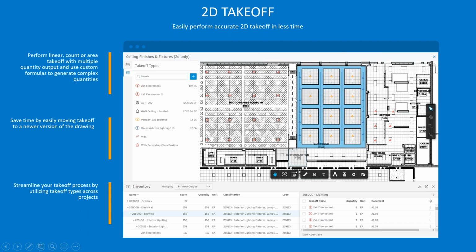I do know that one of the nice features of Takeoff is when you do regions like this, you can create punch outs. So if you identify an entire area, something might seem simple, but you can do these punch outs and it's only calculating that area that's kind of inside that hatch region for you. You can pull those and assign them to different classifications. So you'll see in this, I don't think this is CSI, but we can use formatting. We can bring that formatting in and we can assign takeoffs specifically to different objects. And this really is a quick and easy way to create takeoffs within your project.